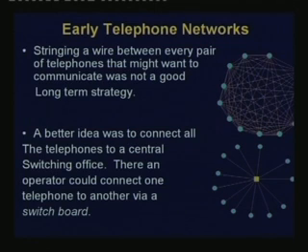As a matter of fact, in the figure at the top, if you have n subscribers, naturally you have n into n minus 1 by 2 links, which is approximately n square kind of links, whereas in the latter case you have only n links. So, the number of links matters as n becomes large, and today there are so many telephone subscribers. So, there is no question of connecting them individually, you have to connect them to a central switching office. And when some subscriber A wants to connect to subscriber B, it goes via the switching office, and finally a connection is made.